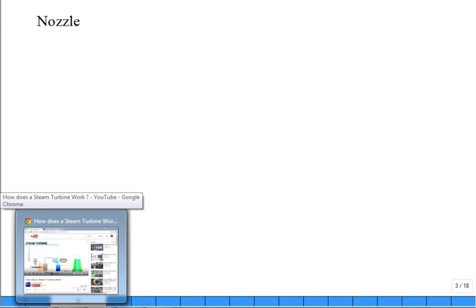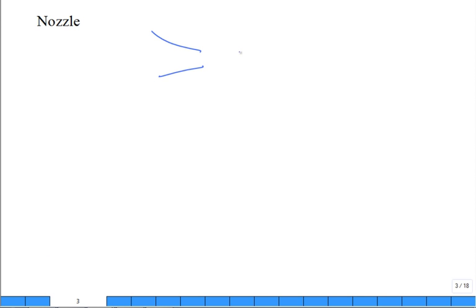We talked about the nozzle last time, did we not? What's the purpose of the nozzle? To really increase the exit velocity. That's the purpose. Is it to transfer heat with the surroundings? No. Is it to produce shaft work? No. It's to come out with a high exit speed. How does it work? You have to push it through the restriction, and so the inlet pressure is greater than the exit pressure. And we solved the problem last time.